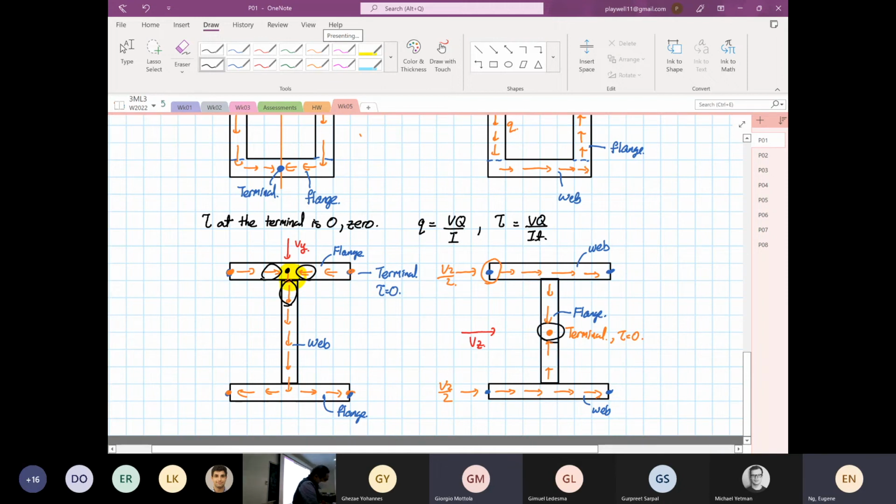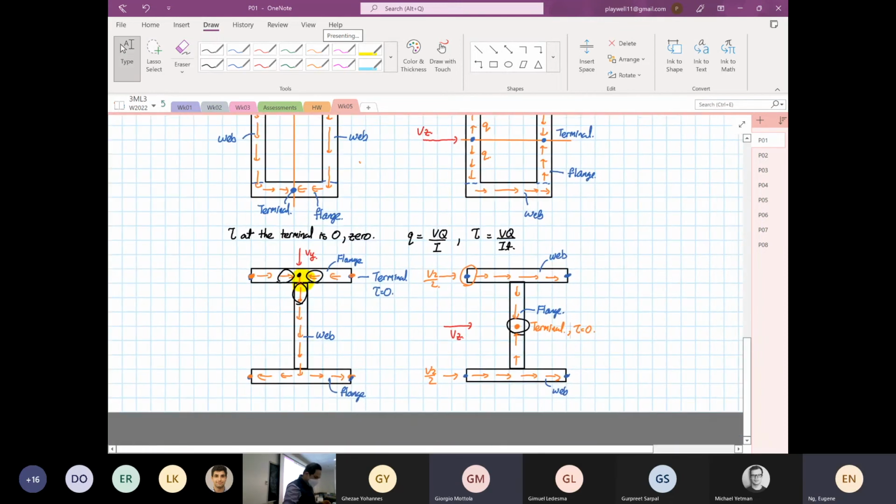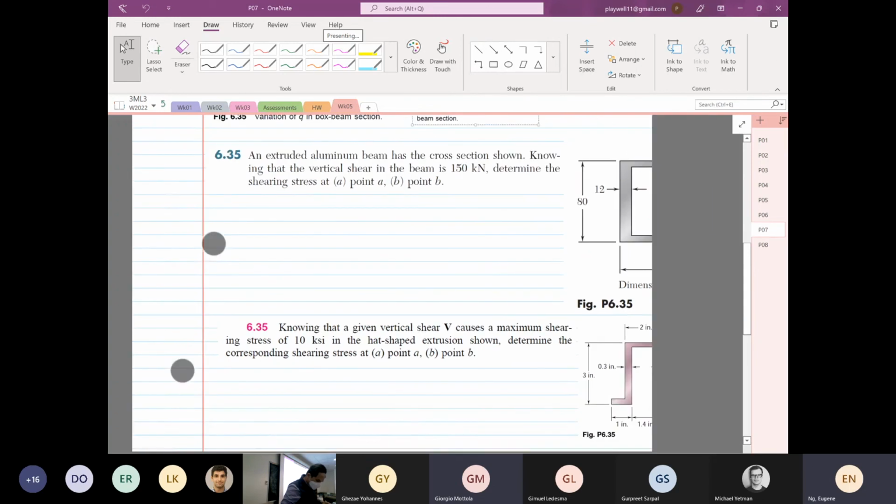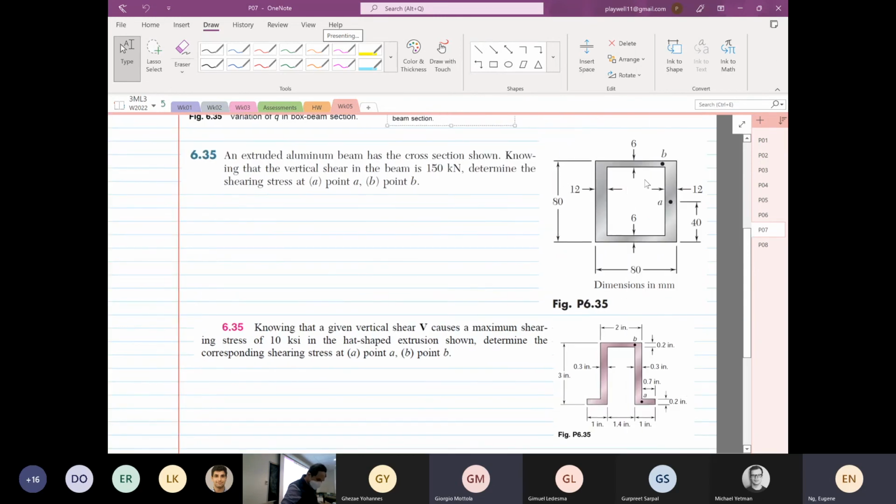That is a very good question. That's really, really a good question. Yeah? It has nowhere to flow, then we classify it as a terminal. Then at the terminal, the shear stress is equal to what? Equal to 0. Okay? Right. So now you can see how we design shear flow. I'm going to make things not ugly, but let's do some example. If I have any, okay, I will draw an example for you.